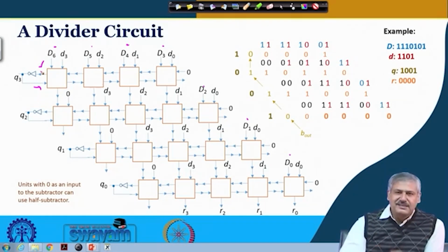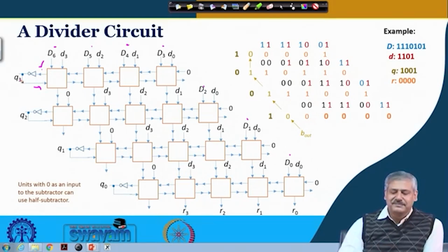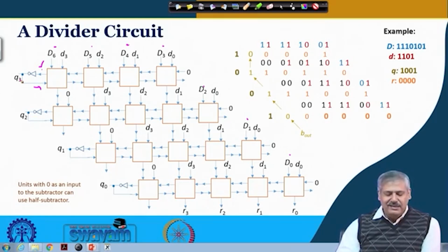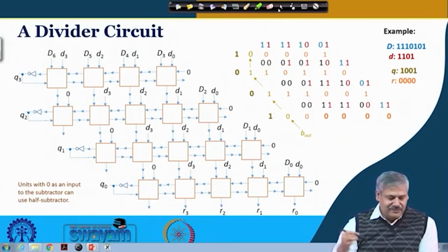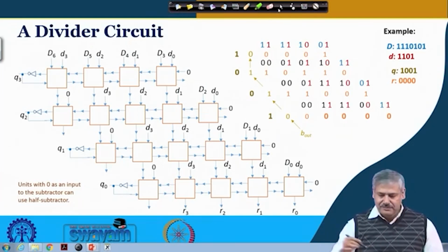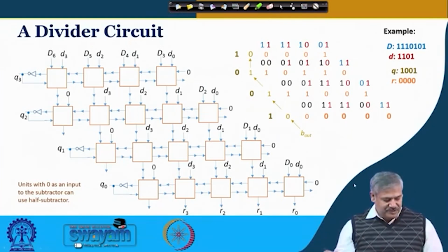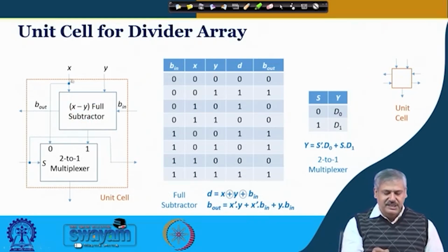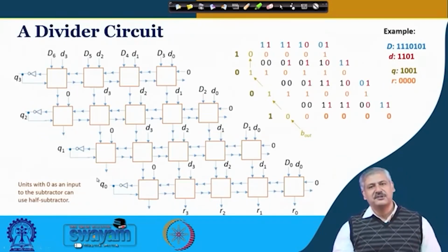So in the final stage, if a carry is generated, so this is 1, then it will become 0. So when carry is generated, then if you go back, if it is 0, then the number from which it is subtracted, the minuend, will come here, and otherwise the difference will come. Is it okay?